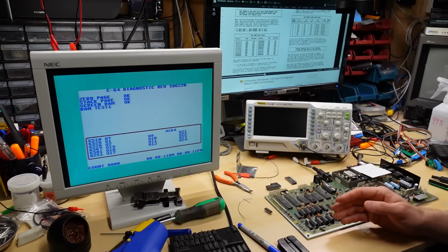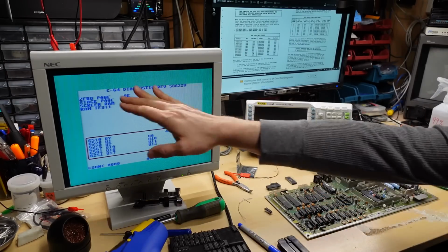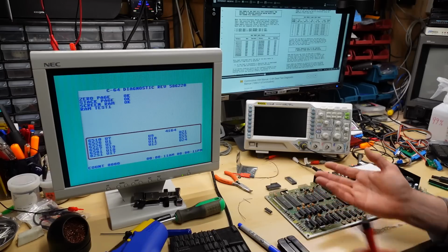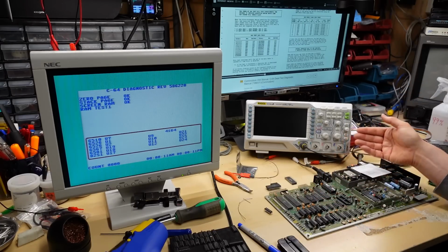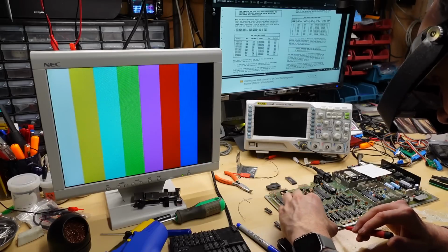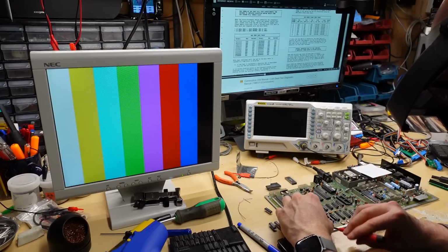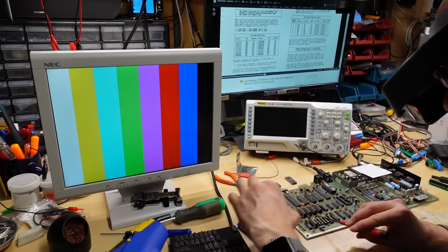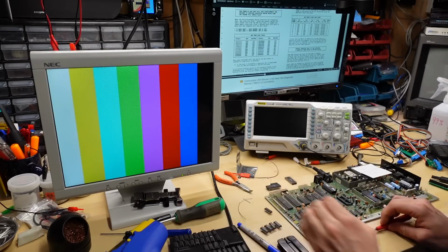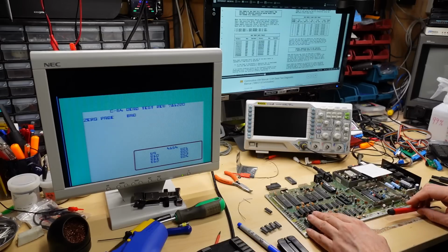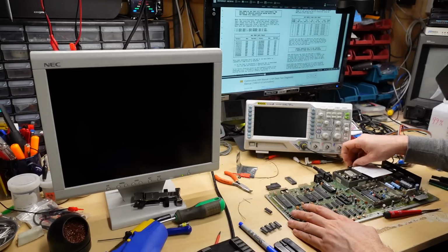And like I said, I tested all of this RAM in the other board, in my ZIF board, and I let it run through the full RAM tests on this diagnostic cartridge, and it was fine. So what's going on with this? I'm just going to remove this TI RAM, and I'll pop in something else, just to eliminate what's going on here. This is so confusing. Nope, I just stuck in different RAM and it still shows as zero page bad.